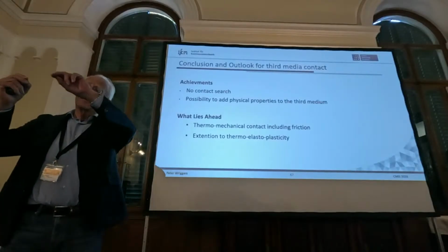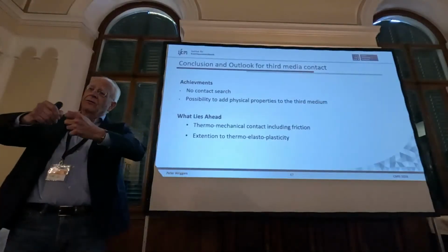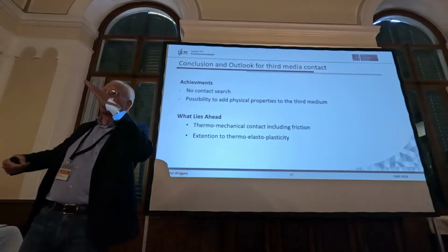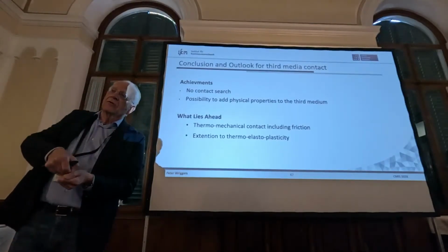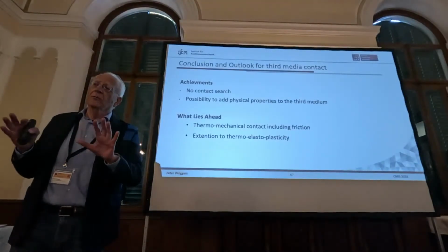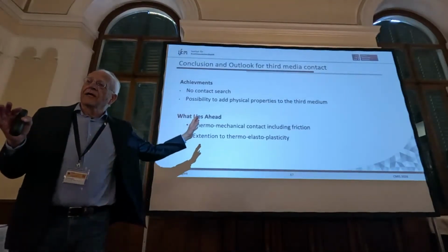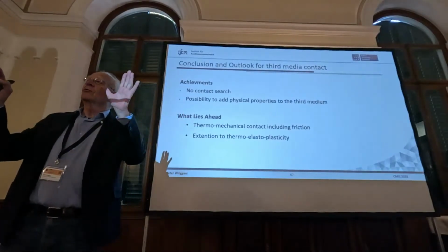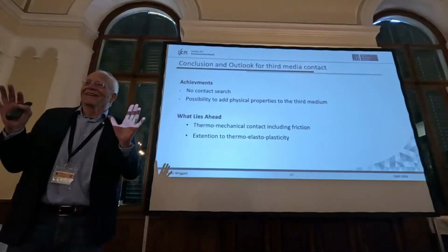that if you have a very large sliding, then you are sort of pulling the element very much. And then if it moves around the contact, then all of a sudden you have a stiffening of your system, which is not correct. So this has a certain range where it works great, but there are some parts where you still have to do the good old contact and everything to get it.